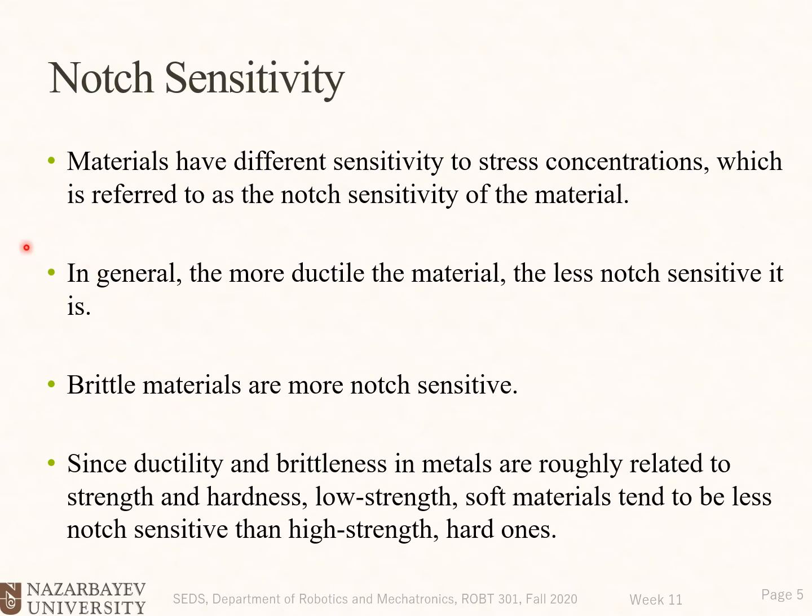Materials have different sensitivity to a stress concentration, which is referred to as the notch sensitivity of the material. So from now on, we are referring to dynamic loads. Notch sensitivity is something that we use for the fatigue stress concentration factor for dynamic loads. In general, the more ductile the material, the less notch sensitive